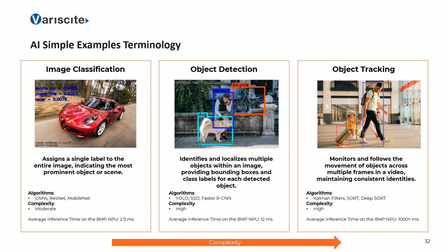An application like this could take 1,000 milliseconds or more on an 8M+, so significant optimization would be required to ensure the platform is suitable. The 8M+ and also the MX93 and MX95 can handle a range of image processing tasks, but the complexity of the application directly impacts the processing time, emphasizing the importance of careful optimization and hardware selection.